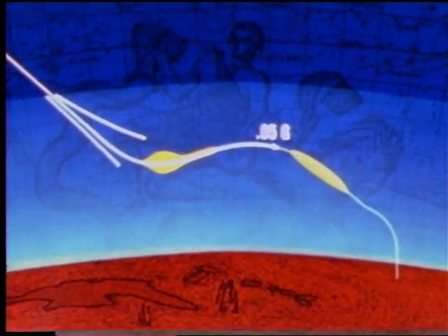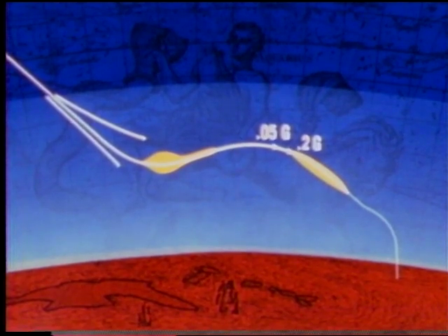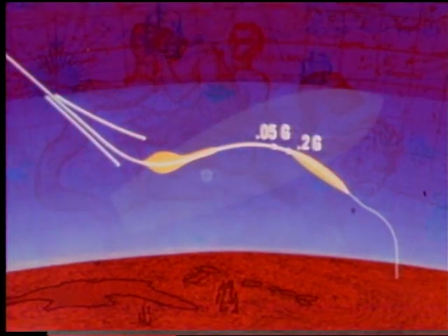The second control period, beginning at 0.2 Gs, will last a minute and a half. While a dangerous skip-out cannot occur, an error could take the spacecraft and crew beyond the stress limits. It is during this second control period that the fine-tuning of the entry trajectory takes place. That is, the spacecraft will be maneuvered to shrink the landing footprint, as determined during the first control period, so that the spacecraft will arrive at the target.